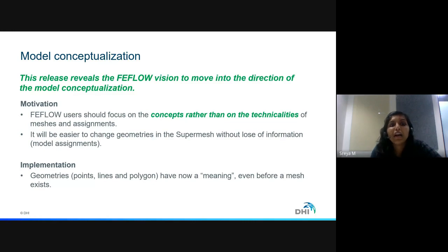Here you have the options of points, lines, and polygons, which are used to identify these features in the model. Lines are used for, for example, a simple river; you use a line structure to define that river. If an agricultural field is there, that region will be defined using a polygon feature, or your model area boundary will be defined using a polygon feature.